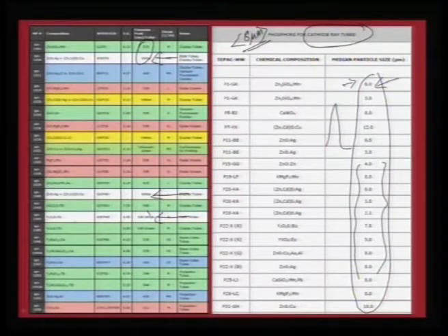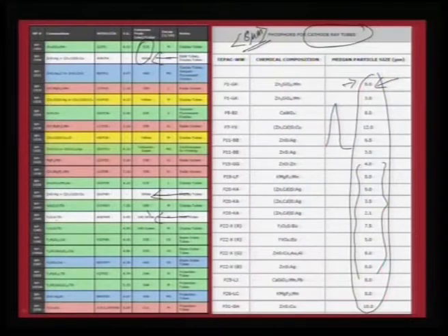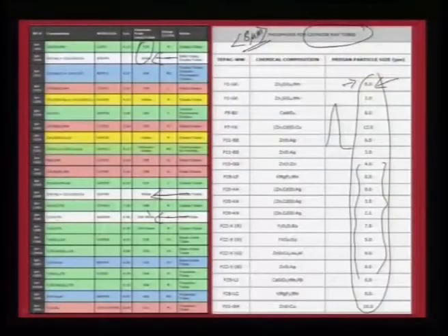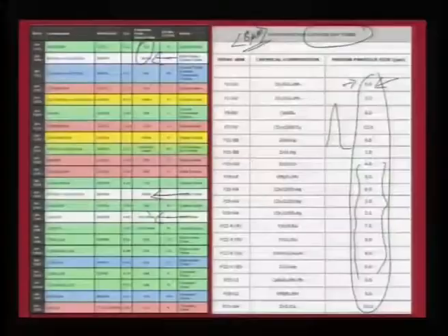and therefore, there are other combinations. For example, if you take yttrium oxysulfide which is doped with terbium from 2 to 5%, then you would end up with white light which has a dominant emission at 545. So, by varying the dopant concentration, it is possible for us to engineer a variety of phosphors, and as you would see here, the range is mainly between zinc sulphide or yttrium based oxides or aluminates.